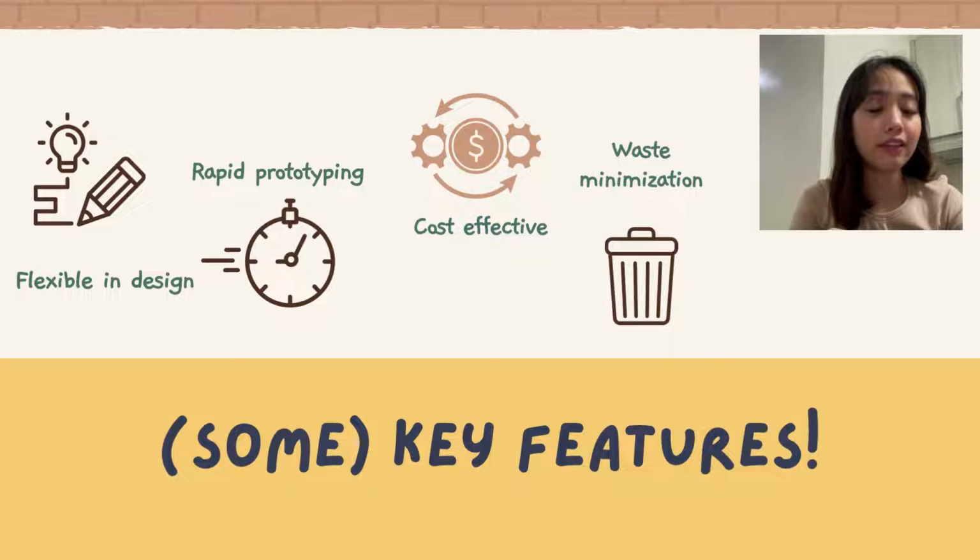Second is its ability for rapid prototyping. The prototyping process is sped up by 3D printing, which can produce parts in only a few hours. This enables each step to finish sooner. When compared to machining models, 3D printing is less expensive and faster at producing components since the part may be produced in only a matter of a few hours. Through 3D printing, time may be saved not only during the part's production, but also during the design phase by producing CAD files that are ready for printing.